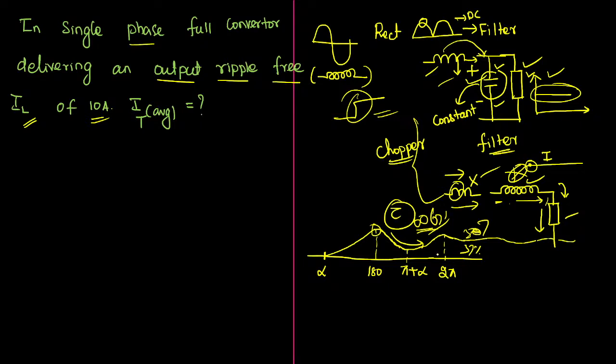That is what we want. If they design it that way, automatically your circuit will become ripple free. That's how people are doing this. So for this condition, what should they give in the question? Either they directly give ripple free current, or they say the value of the inductance is very large. Then by default you have to assume that the output current will become ripple free. Ripple free means you are receiving constant current. In the output we are receiving pure DC, you can also assume that. That's all.